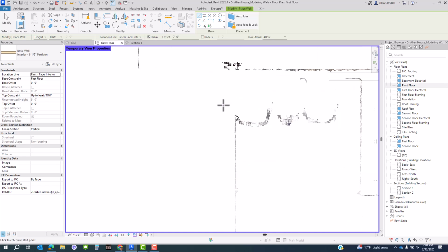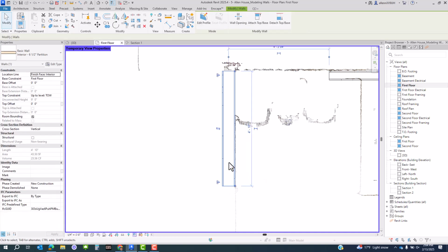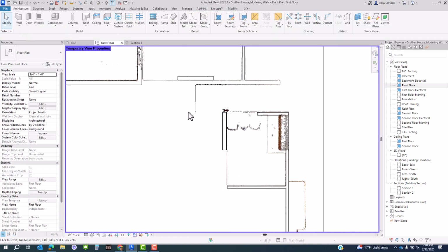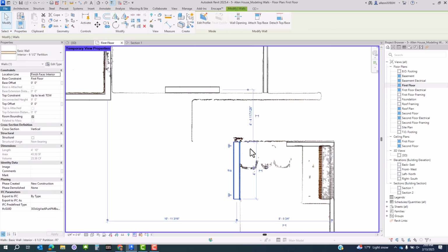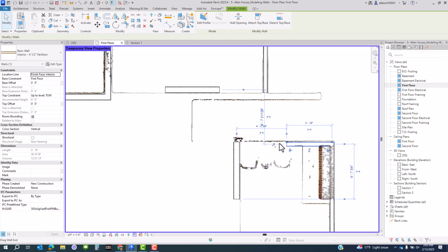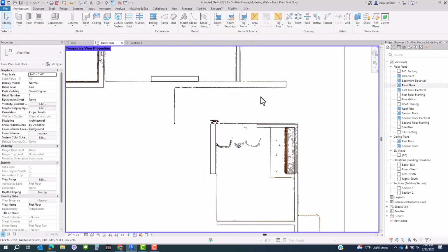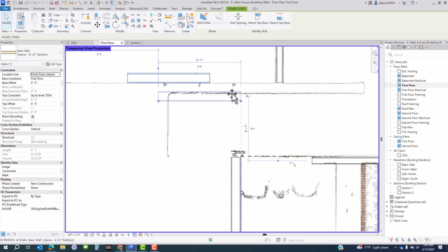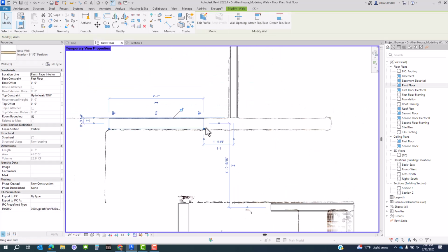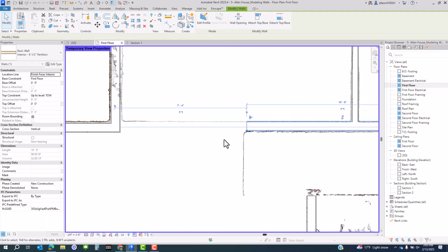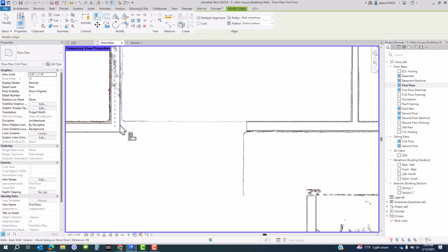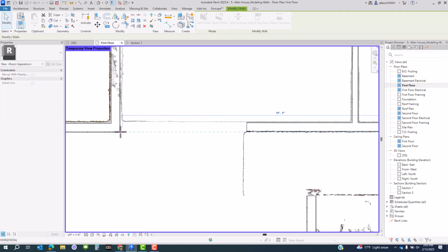But I just want to point out one of the things we may run into is the simple fact that I think I have thicker than 1/2-inch sheetrock on some of these walls in my house. Even in places where it wouldn't really make sense, where there wouldn't be any code requirement for it, I've just noticed that as I've done some remodels, there are several places where I sense a thicker sheetrock. So if you run into that, just either leave it alone or recognize why your wall doesn't line up, and maybe you can change the thickness of the sheetrock for this 2x6 wall.